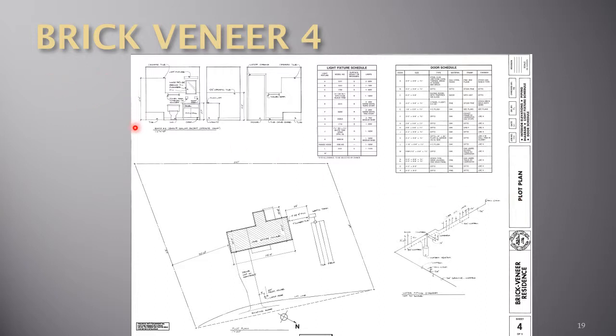Oftentimes, designers will want to minimize the number of drawings, and they will fit information like this wherever there is empty space on a drawing rather than create another drawing. I believe it's a bad practice, and if you can, you should avoid it, especially with today's AutoCAD systems. But it is a reminder of Rule 1 of print reading, which is why you never accept a single plan out of a multi-drawing set.